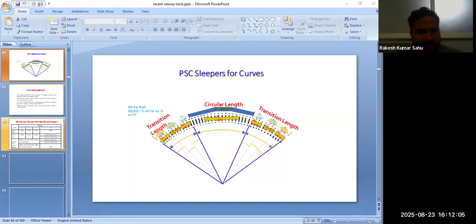Two main parameters are resistance against deterioration, that is weathering and dynamic condition, and longitudinal forces to resist rail creep and contact pressure. Contact pressure comes from toe load. So different types of fastening we use. First one is rail free fastening, second rigid fastening, and third is elastic fastening.